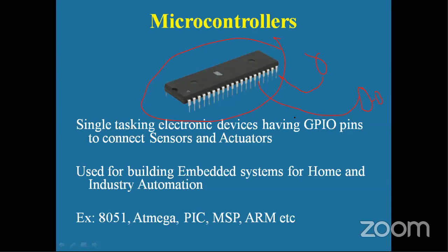So then you will ask, do we have to write the program in hex language? We don't know this programming language. No, you don't have to write hex programs. You have to write your programs in C only. Then we use an intermediate software which will convert our C program into hex code, and then we put this hex code into the microcontroller. Then the ALU understands hex code and executes it. This is for your information.